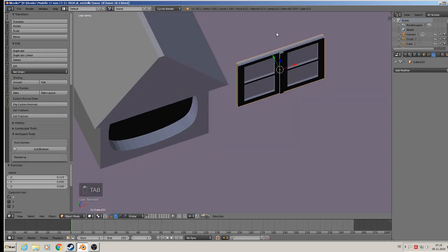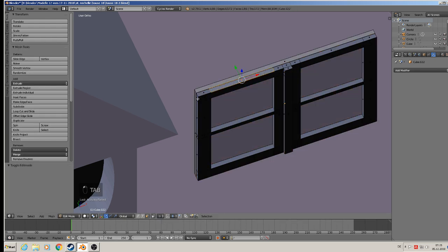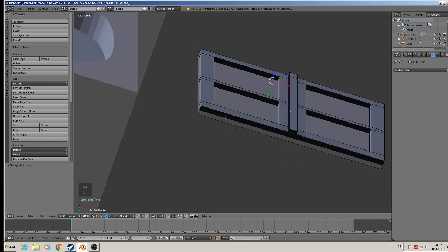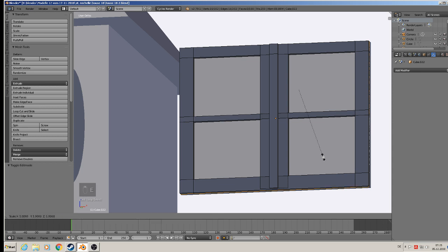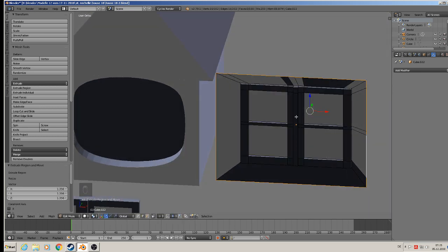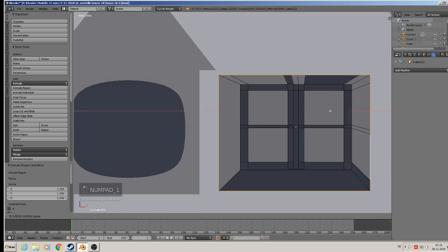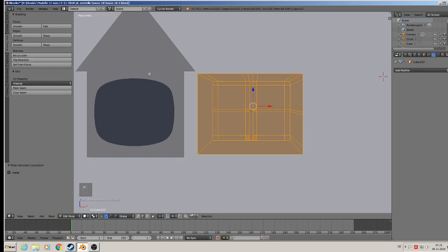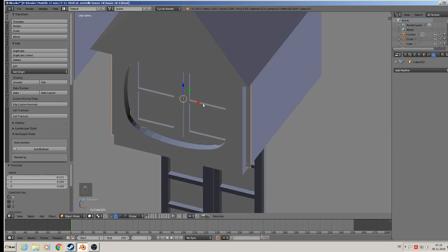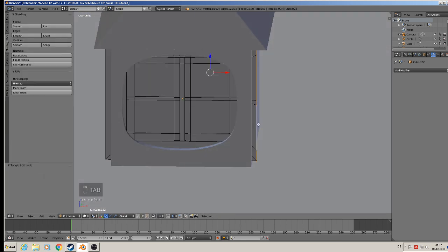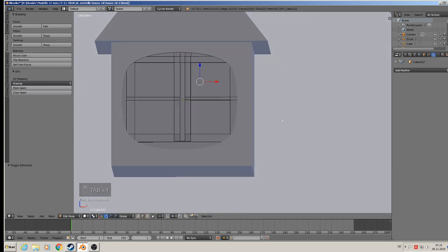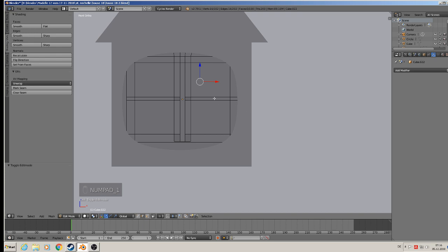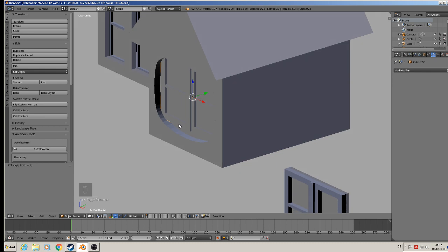So because of that, I take here the backline complete. And extrude scale them. So we have that. Then position them and take all, go to UV shading and recalculate normals. Then we can plug them into. Make them a little bit smaller, but that is okay then. That is like they build it, that's not my favorite, like they build some, but okay, they do it so.